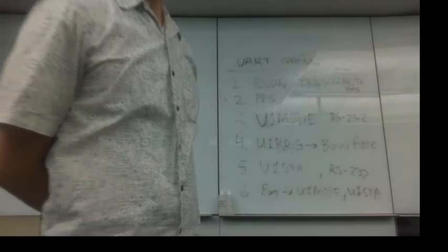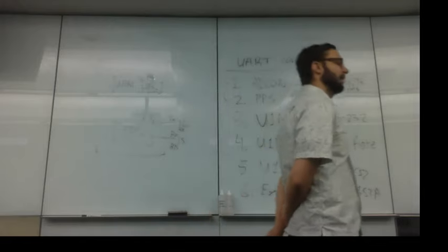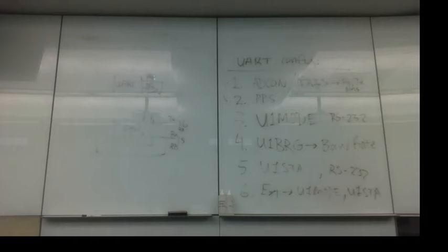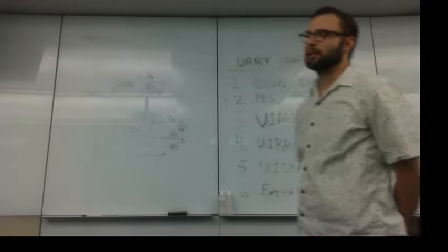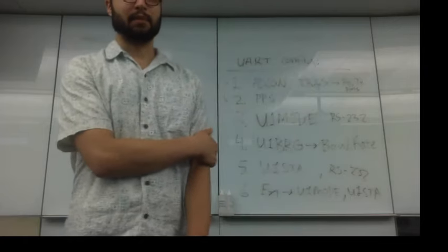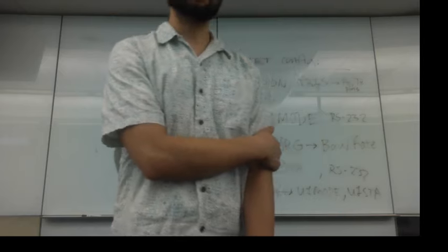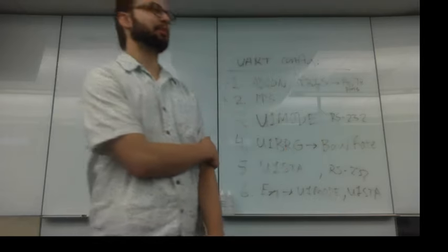So the RS-232 connector, in the lab, I believe you'll have a USB to RS-232 converter, which you can put on your breadboard. Does anyone have them already, or do they get provided in the lab? I should probably know that. Nobody has them. Okay. So you may or may not have to wire this up, but basically pins 2 and 3, if you look on the connector, are the RX and TX. The rest of the pins don't necessarily need to be implemented.